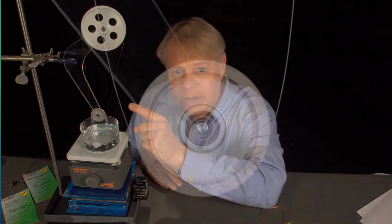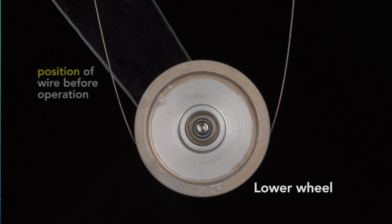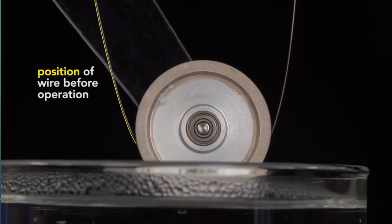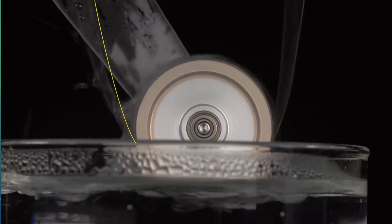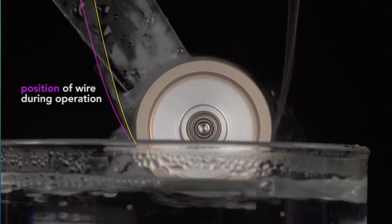This engine runs because this loop of nitinol wire was originally straight at a very high temperature, so as it's heated, it tries to straighten. To see how that causes the engine to operate, watch what happens as I contact the lower wheel with the heated water. I'll mark the position of the wire on the left with a yellow line. Then, when I start the wheel, the wire's distance from the initial position is much greater. It's hard to see, so I'll mark its position with a purple line.